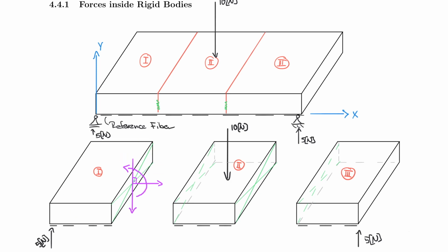All right, now we have one system in equilibrium. The next easier one is probably the part 3 here. So the system 3, let's put that into equilibrium. And yes, you guessed it, we of course need a shear force, a normal force, and a bending moment as well. So let's introduce those forces too.